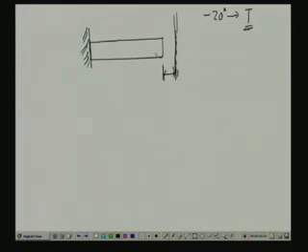initially when it starts expanding, it goes up to the wall without any problem. Until that time, since it is not experiencing any obstruction, the bar will expand freely, and thereby there will be strain, but there will not be any stress in the bar.